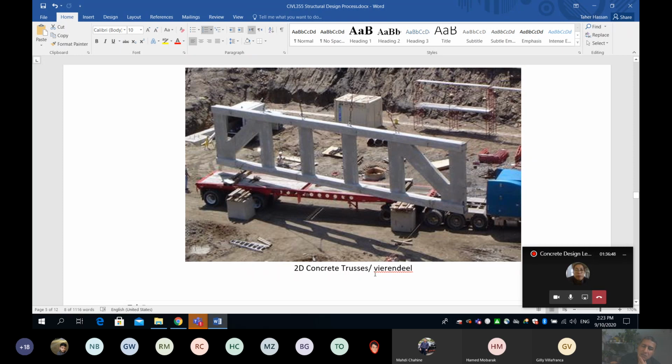So that's why in my title there, I called it trusses / Vierendeel, because it's not really a truss. From here to there, it's Vierendeel. This part here, it's Vierendeel. However, this last bay from each end is a truss. You guys know what it means, truss, huh? The truss means all those bays must have a diagonal. The diagonal is the secret, okay?